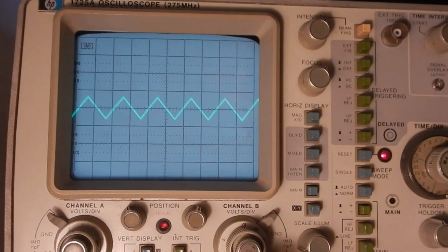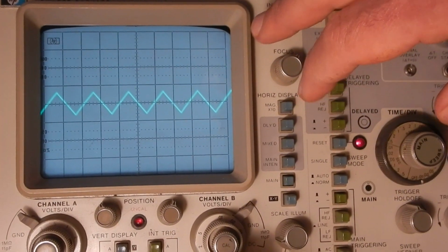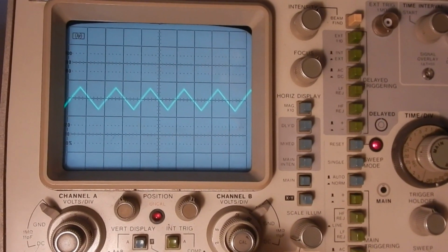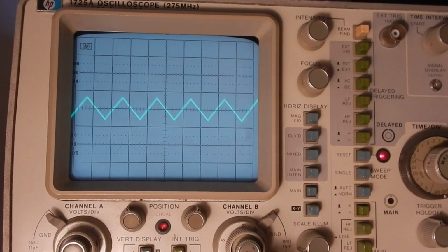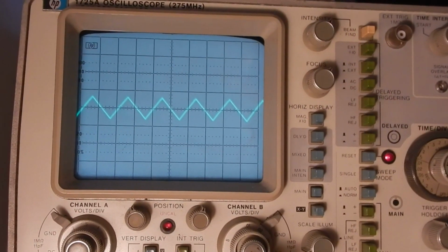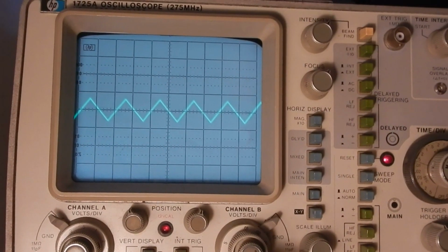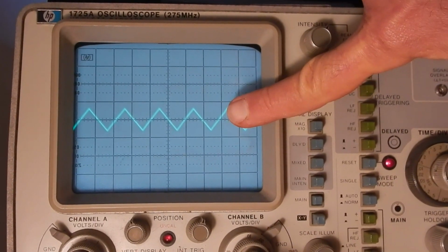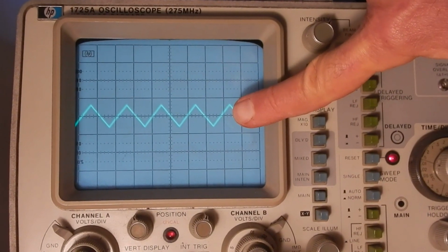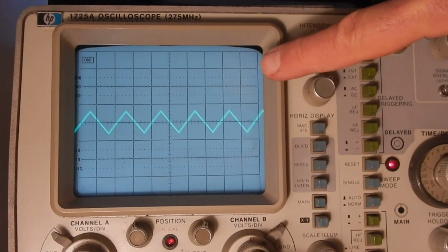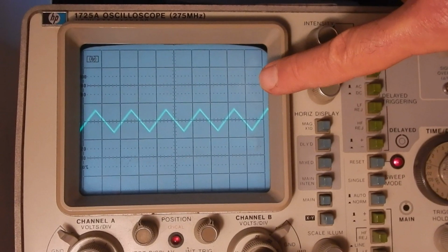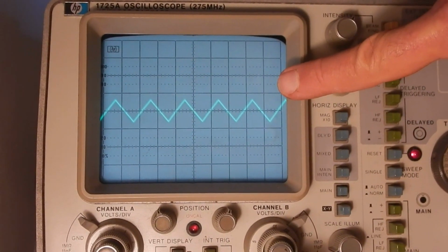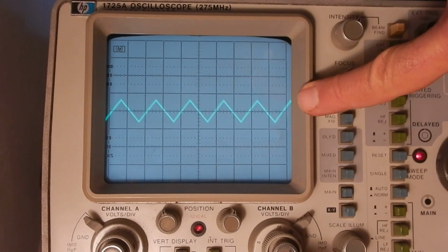Not too bad, but the frequency of this signal tells me the regulator chip on this circuit is not what is printed on its case, because this frequency is exactly 50 kHz, while the real chip should oscillate at 150 kHz. So the chip is clearly a fake.